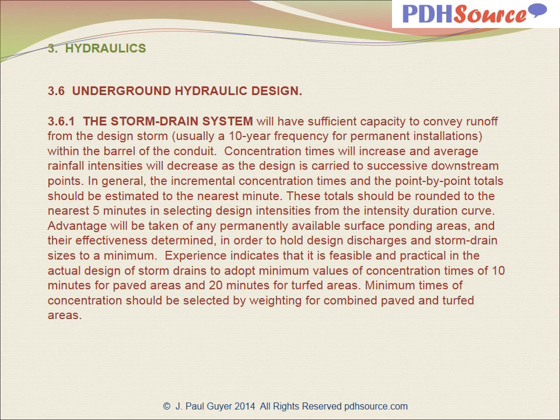Experience indicates that it is feasible and practical in the actual design of storm drains to adopt minimum values of concentration times of 10 minutes for paved areas and 20 minutes for turfed areas. Minimum times of concentration should be selected by weighting for combined paved and turfed areas.